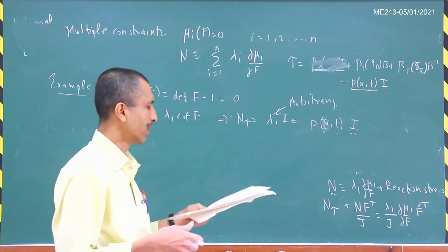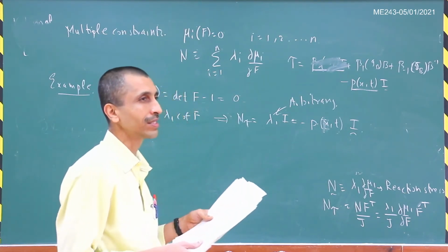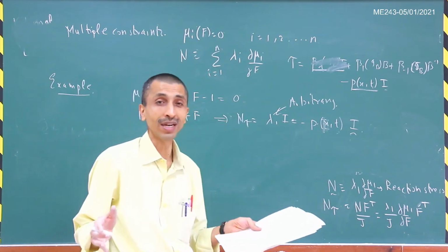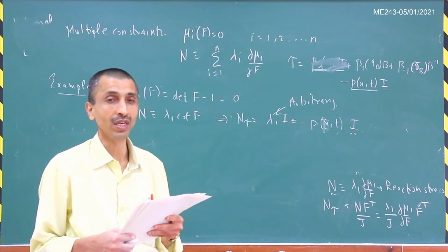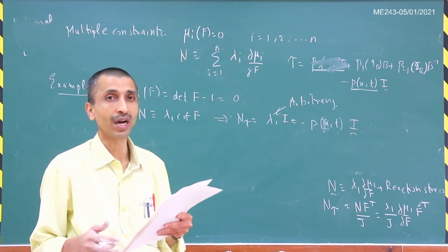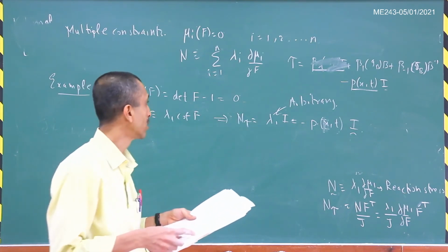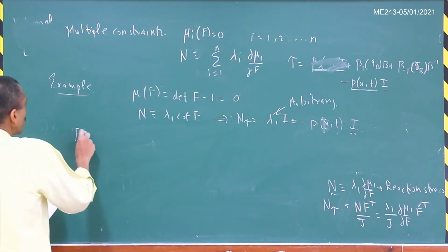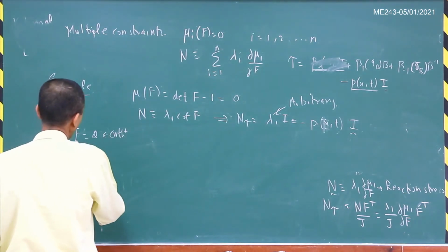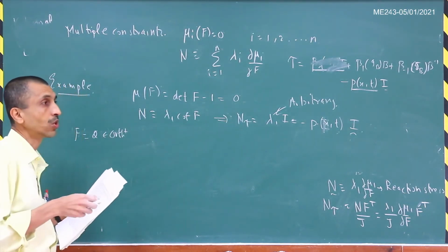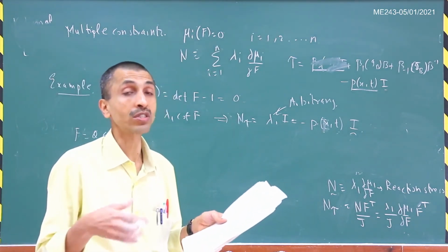So I will not go into that, but one can deduce it. One interesting case is that if the body is rigid, then all the components of the deformation gradient are constrained, because in that particular case your F has to be equal to Q, which belongs to our class. So all the components are restricted, and so the entire stress tensor in a rigid body is constitutively indeterminate.